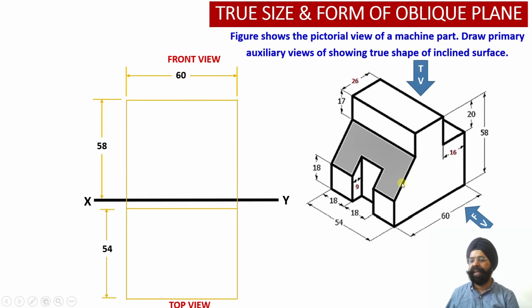So this will provide us with the edge view construction of the cut section. This is the inclined cut surface section, so we have to obtain the edge view of this inclined cut surface section in the front view. Let us proceed with the different elements of this solid. As we have discussed, on the left hand side, the height of this vertical element of the solid is 17 millimeter. So once I mark this height equal to 17 millimeter, a horizontal projection line is drawn.